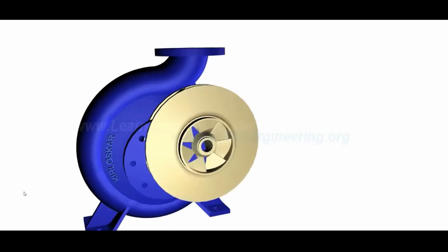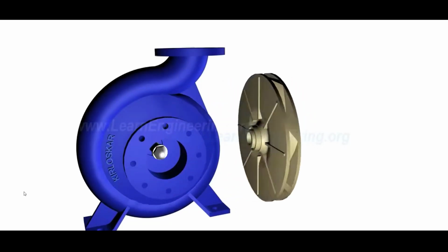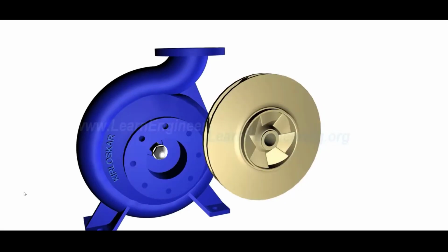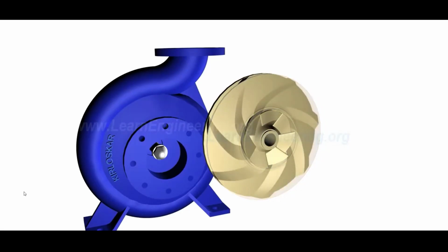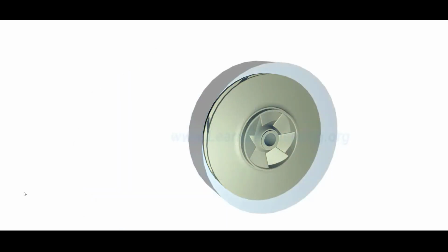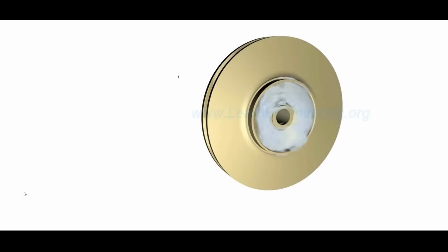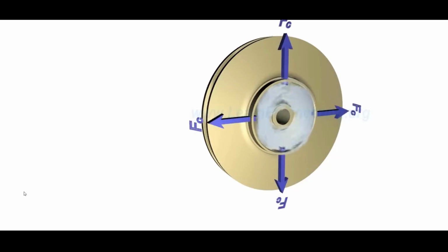At the heart of the system lies the impeller. It has a series of curved vanes fitted inside shroud plates. The impeller is always immersed in water. When the impeller is made to rotate, it makes the fluid surrounding it also rotate. This imparts centrifugal force to water particles, and the water moves radially out.